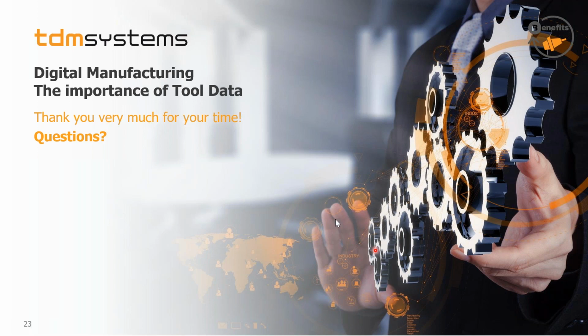If Mark Aurelius is still here, maybe just an add-on to the speeds and feeds question. I think my answer was a little bit misleading. One is really just about the tool life monitoring, and you're talking about speeds and feeds. It is really about we manage them, and you have your original values you get from the vendor, and then of course you can add additional information based on your knowledge and your historical values. We can also add multiple speeds and feeds to, for example, a tool assembly. So if a tool performs differently on different machines, you can add this, and those speeds and feeds are also automatically transferred through the CAM interface to the CAM system. So you set it up in TDM, you call it up from a CAM system, and the right speeds and feeds are automatically transferred to the CAM system for programming.